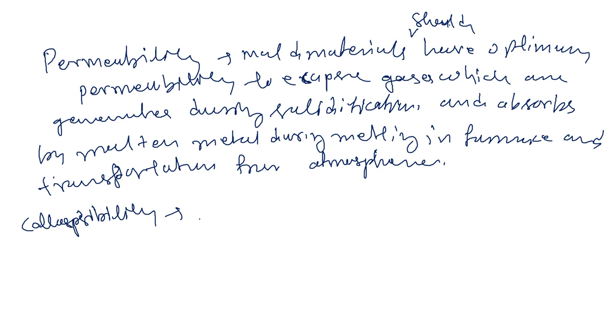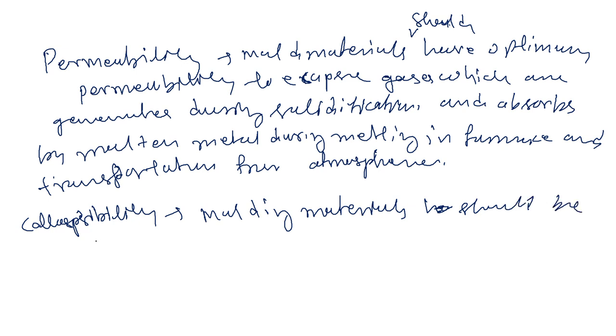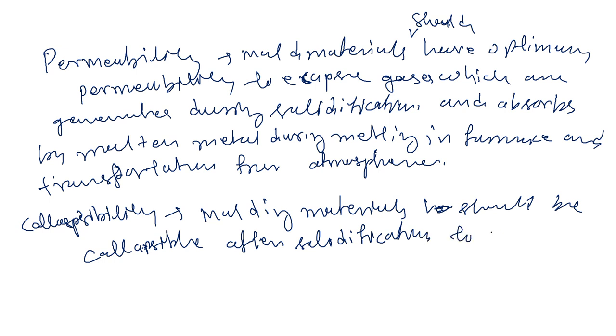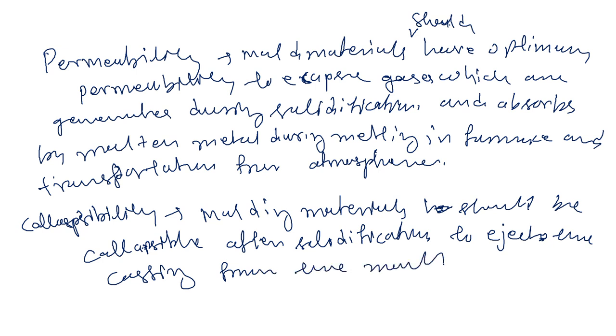Mold material should be collapsible. Molding material should be collapsible, to collapse after solidification to eject the casting from the mold.